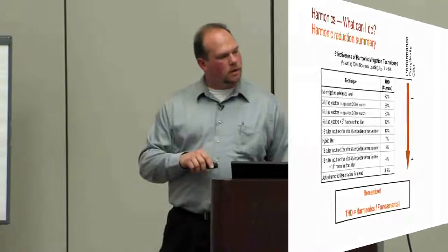One thing to remember is it's a ratio, right? So our harmonic content divided by our fundamental. So remember, if you want to offset some harmonics, increasing your fundamental will help you.